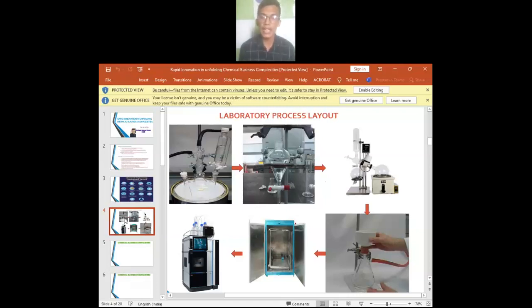What is left behind in the round bottom flask is the distillate, and the condensed solvent is collected in the receiver flask. That is nothing but recovery solvent. The distillate is then isolated for final product and filtered through Buchner funnel setup in case of laboratories and centrifuges in case of production plant.